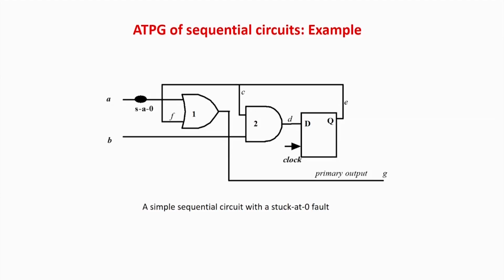In the last class, we took different circuits and saw that there are two ways of testing. One is called the random pattern test, and the other is the sensitize, propagate and justify kind of test, where difficult faults are tested. For sequential circuits, we will mainly focus on the sensitize, propagate and justify approach, because the complexity starts when we go for such difficult-to-test faults.